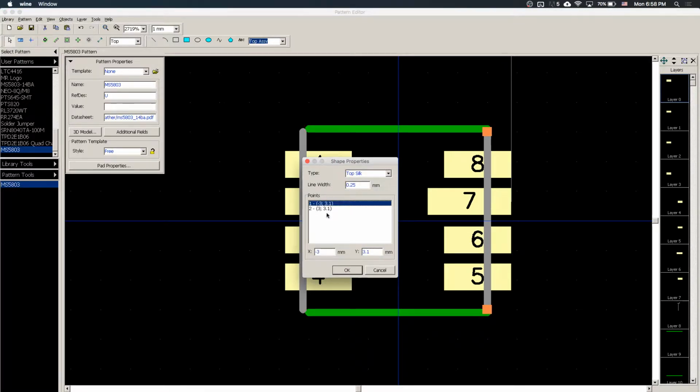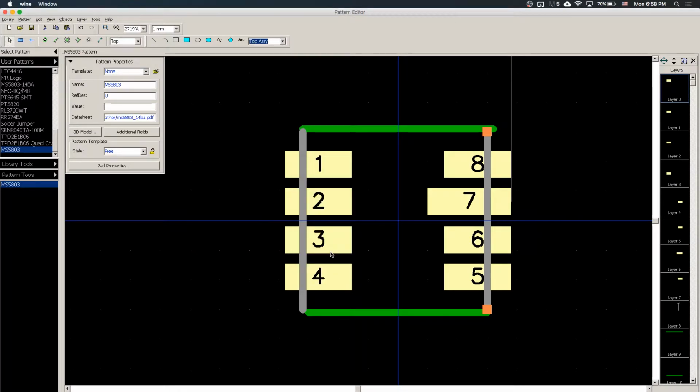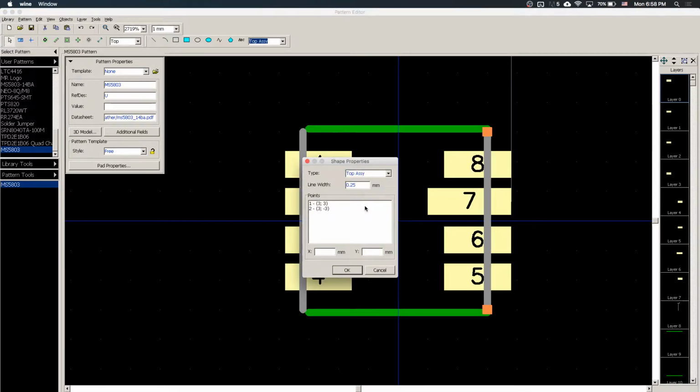The gray line helps you indicate the construction you put in to create this component, and the green one is the one that will get printed onto the board to indicate how the component is oriented and what its physical dimension is. Sometimes you have a lot of things crammed into a very short area, so it's better for you to know which one is what. Click on 2.